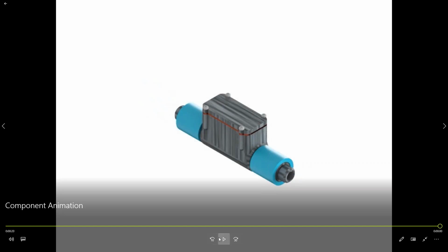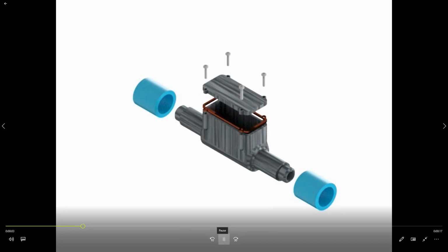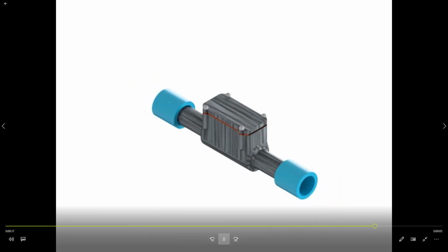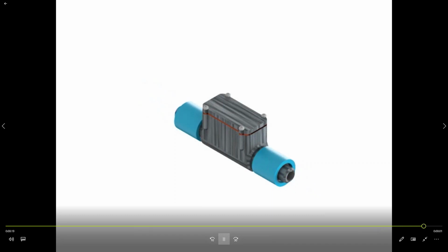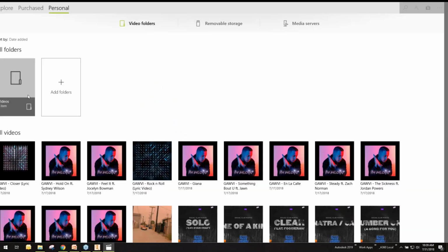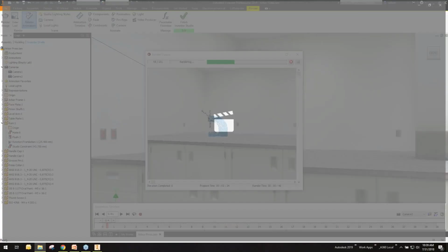But then I also had to move it out into space, and that was again an instantaneous move. And then I had to animate putting it back together. So each component had 3 separate animations on it technically. One to suppress a constraint, another to move it out in space, and a third one to move it back into position. So let's see here, one more.